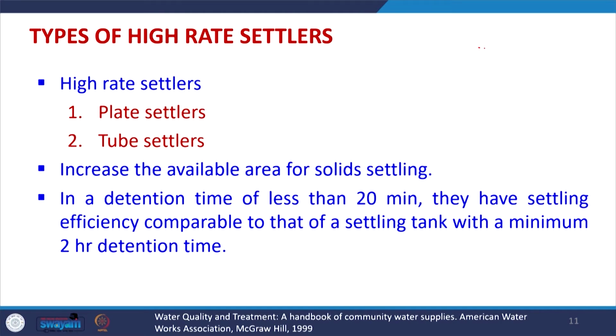Actually, the earlier design was that, suppose this is the simple horizontal flow settler. Any particle entering here, the earlier consideration was that it should settle down before it leaves. So, that means the depth is less, and under that condition the time of settling will be much less.